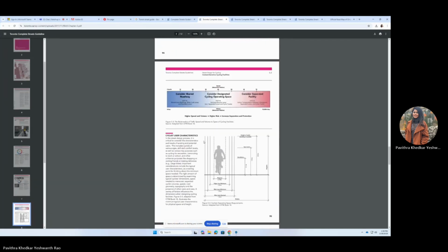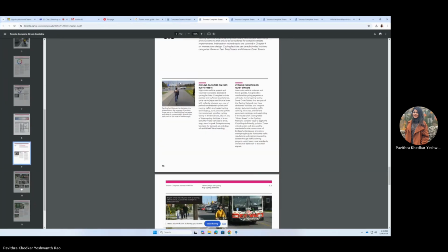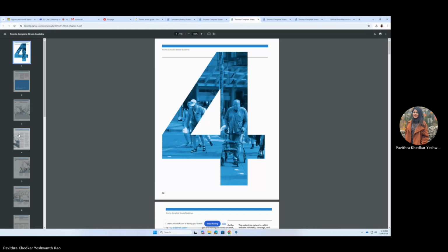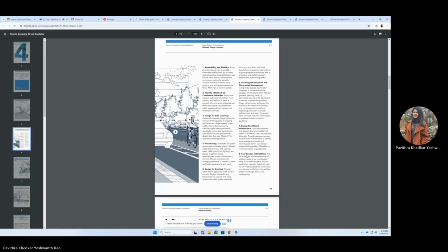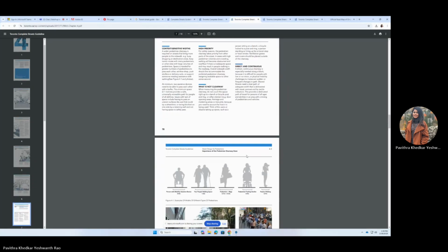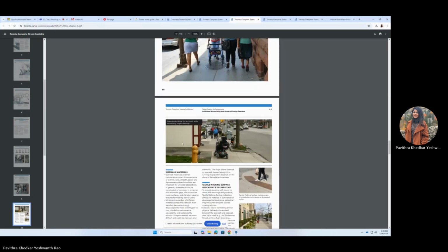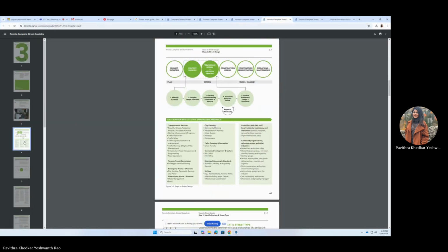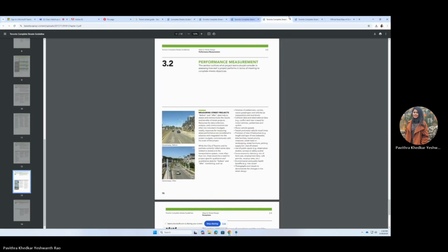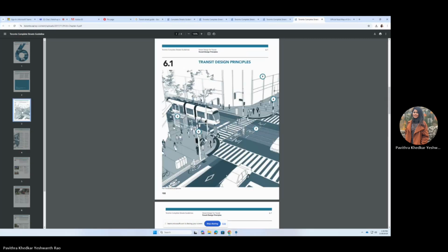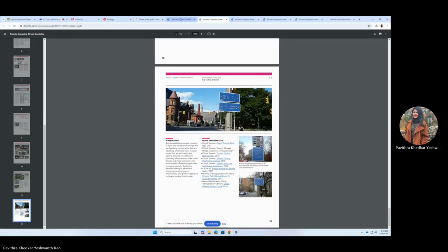Follow transit principles to accommodate public transportation lanes, stops, and transit-oriented planning. Consider street width, sidewalk space, bike lanes, and vehicle lanes based on city guidelines. Ensure pedestrian accessibility by incorporating clear pathways, crossings, and barrier-free design features. Balance functionality and aesthetics by integrating landscape, lighting, and seating where applicable. Maintain flexibility in your design to accommodate further urban development and transit improvements.